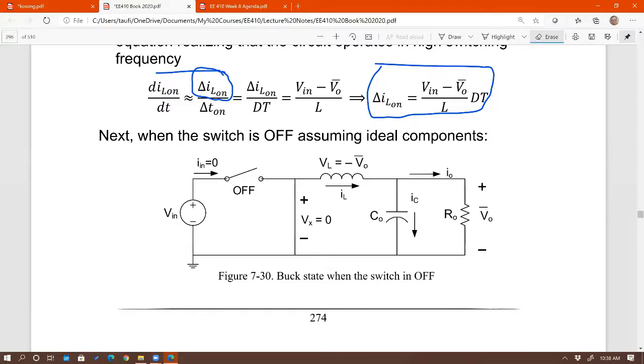That's why we need that inductor as the energy storage, so that when the source is disconnected from the load, this load can still receive energy from the inductor. In other words, when the switch is off, this inductor must discharge its energy, must release its energy. Agree? When it's releasing this energy, I know that the reference voltage is plus minus that way, as I just explained earlier. But the instantaneous voltage of this inductor, what's going to happen with respect to the reference voltage? Anybody?